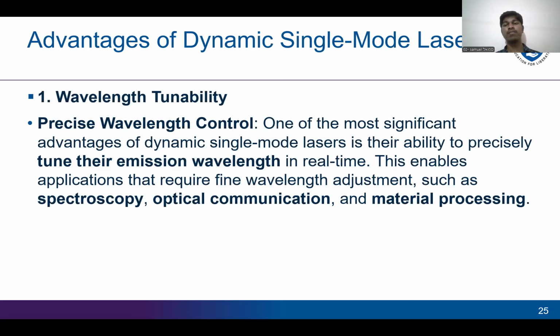Advantages of dynamic single mode lasers. Wavelength tunability. One of the most significant advantages of dynamic single mode lasers is their ability to precisely tune the emission wavelength in real time. This enables applications that require fine wavelength adjustments such as spectroscopy, optical communications, and material processing.